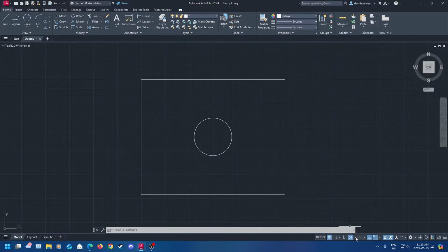If you are having issues with snapping, one thing you can do is come down here in the bottom right hand corner. You're going to have tools down here that help you determine what things will snap to. So if you click on that arrow there, you're going to see you can select 90 degrees, 180 degrees, whatever. We're not really going to deal with that, but if you come to this one here, this is going to tell you where your cursor will try to snap to. I recommend you set everything I've got here.